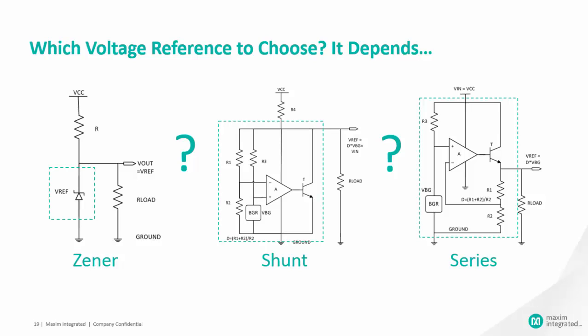Finally, should you use an LDO? The answer is yes, if your requirements for accuracy, tempco, and noise are not too demanding and you need high current capability. For more on this subject, please refer to Maxim's tutorials number 4003 and 719.